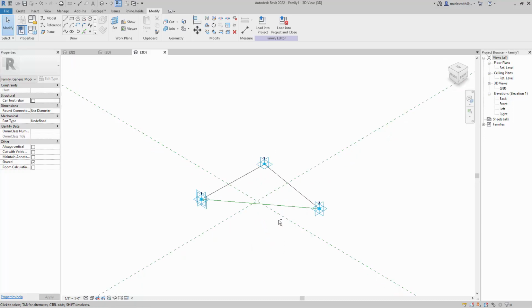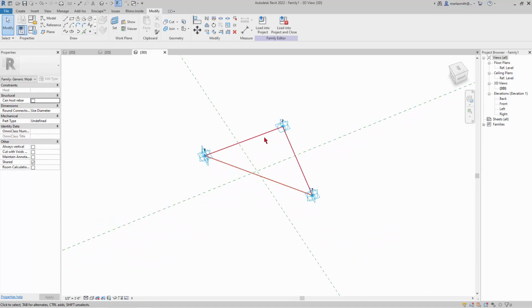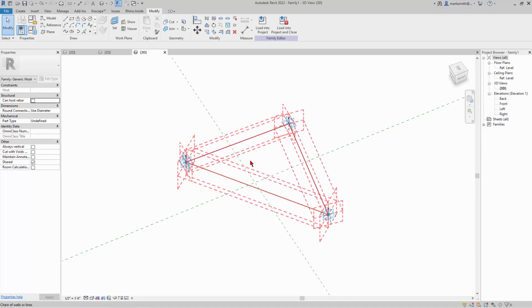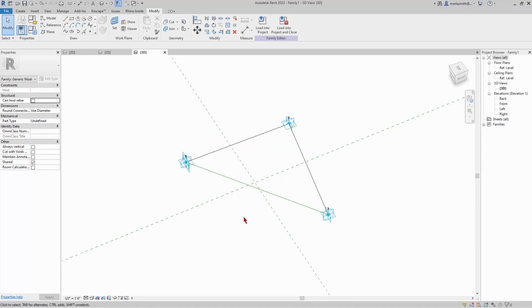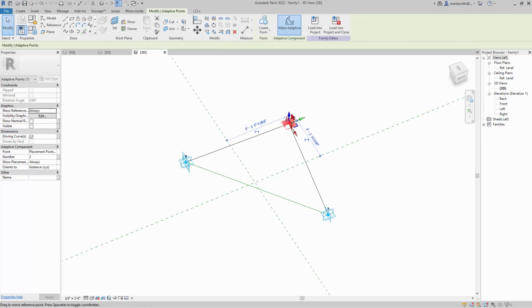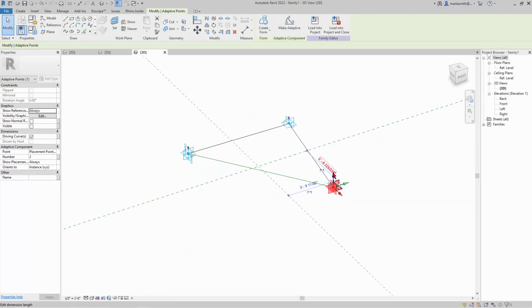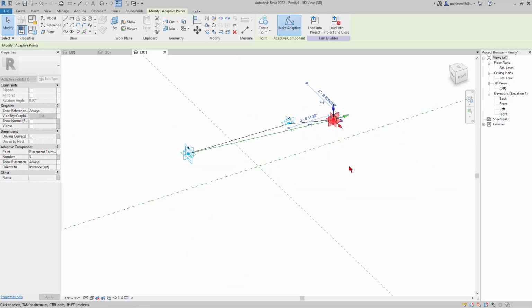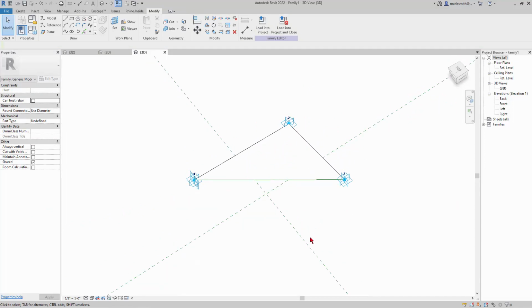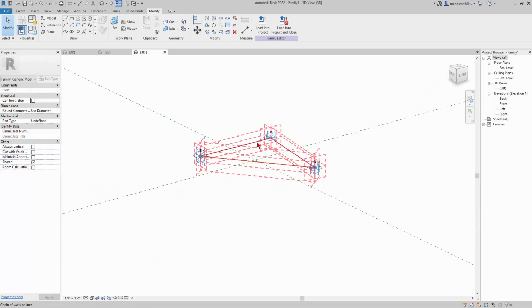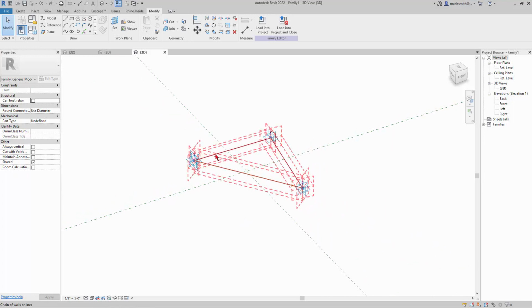So now that I've got that, I actually have a little surface in there. It's a little hard to see because the things are coming through it. But one thing you want to do once you get this is come in and grab one of these points and get the Z and kind of pull it up and make sure everything's following and things aren't breaking. You know, like lines aren't staying behind and surfaces aren't staying behind. So you should be able to have a form element, these guys, and actually your lines stay behind, so you kind of have this. So the next thing I want to do is just go in and pick the form